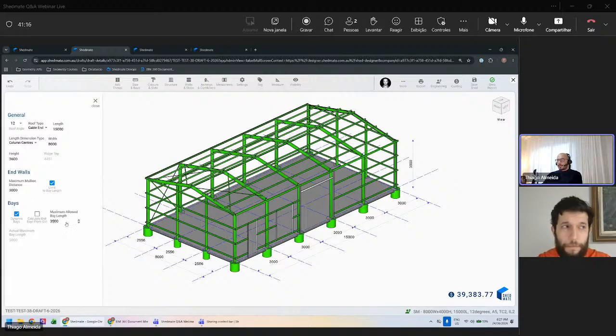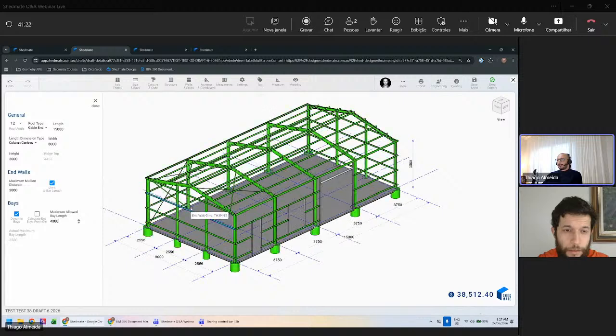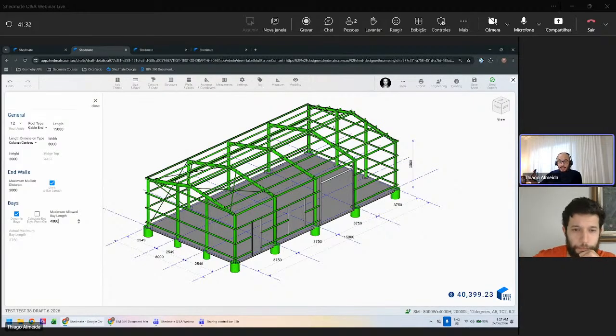So if I want to, I can see in here, hey, what if I allowed it to go to 4 meters? Will that make any difference? It will. And you can see the back and forth result and the engineering automatically applying that information directly to my shed right now, because my frames change, my frame sizes change, and all these footings and all these things automatically are applied because I had that configuration, right? The auto apply engineering setup.